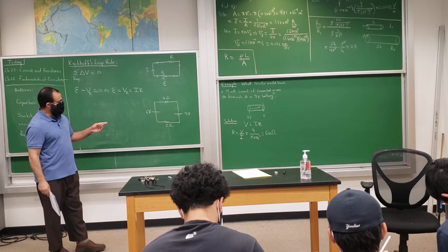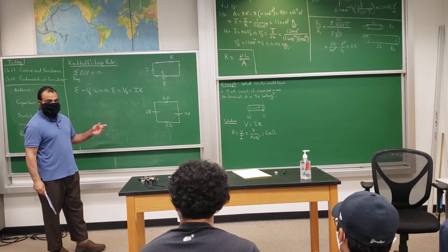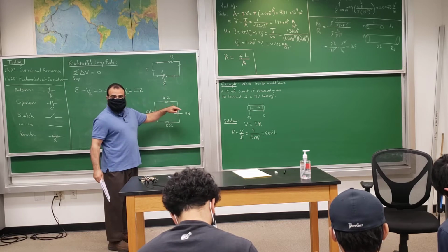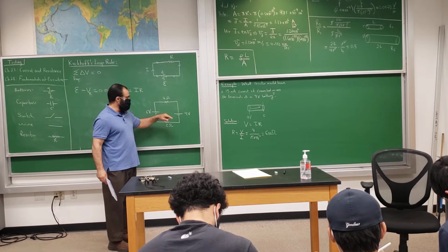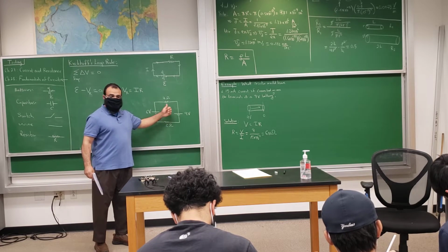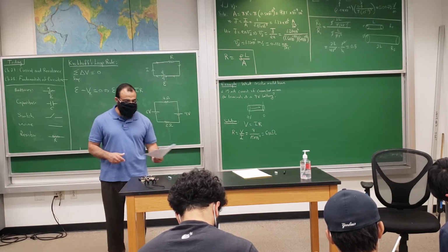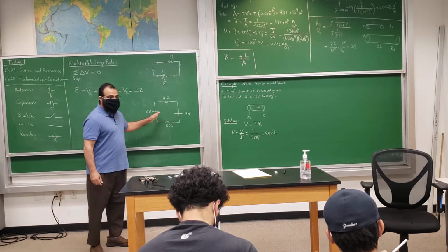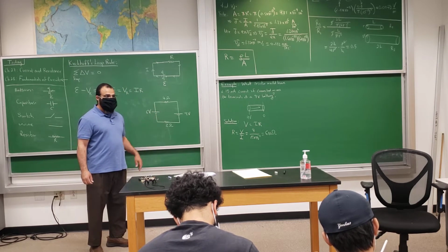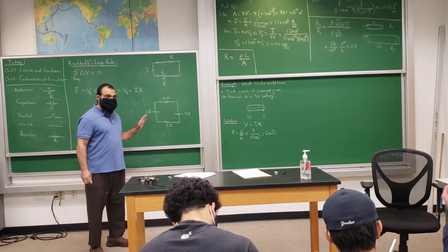Now these two batteries, are they connected in a good way or in an efficient way or a bad way? It's a bad way. This is trying to push positives this way, and this one is trying to push them against it. So they're not helping one another. So it's like you have 2 water pumps. One of them pumping water this way, and the other one trying to pump it against it. So effectively here, we really have a 3-volt battery. That's effectively what the voltage is. Intuitively, that's what's happening, okay?